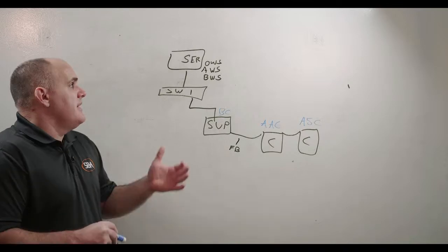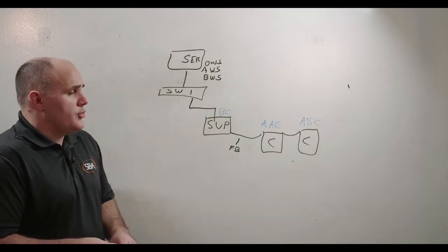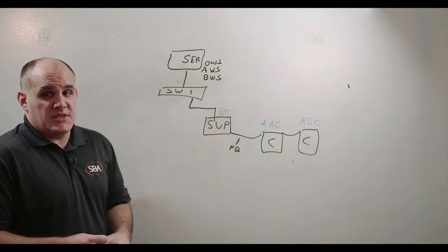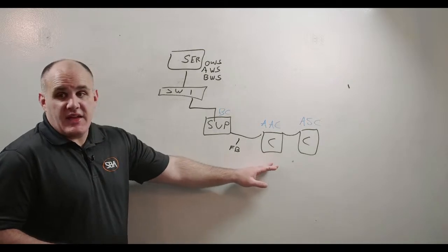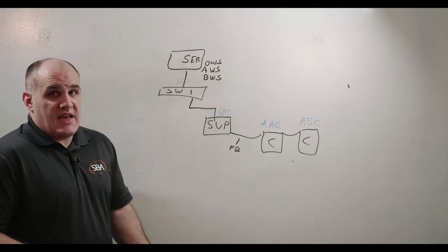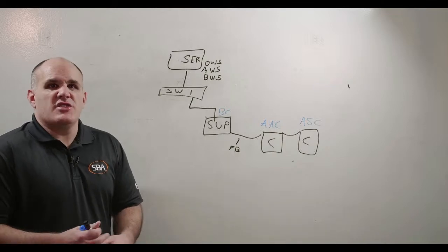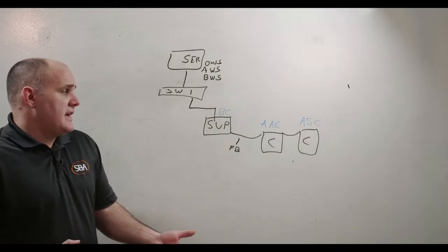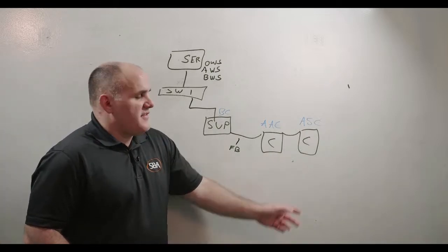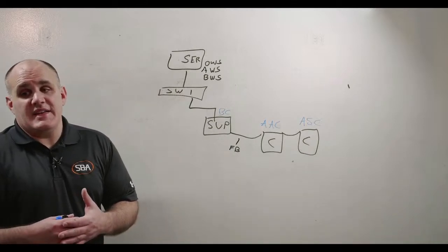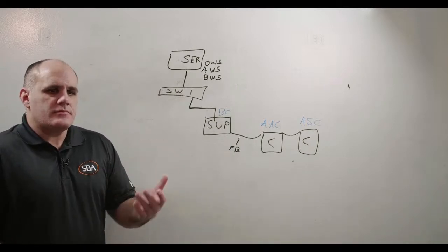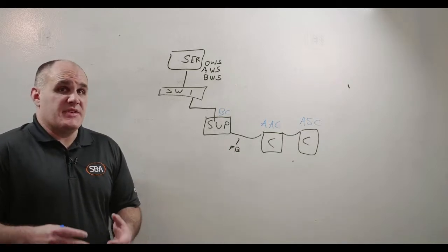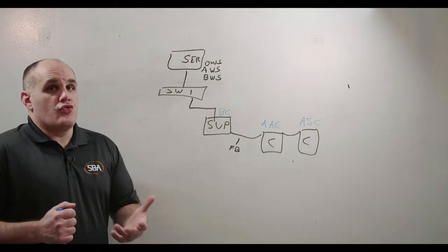So to recap, commonly we have a 4-tier architecture. We have servers. We have supervisory devices, also known as building controllers in some specifications. We have advanced application controllers, also known as AACs, also known as IP controllers, also known as supervisory devices with I/O capability in some cases. And then we have application-specific controllers, which act as either a terminal unit controller, a rooftop controller, anything that is specific to an application and that you're not really going to be able to interchange.